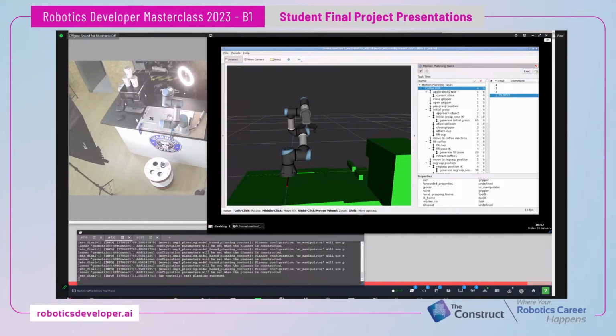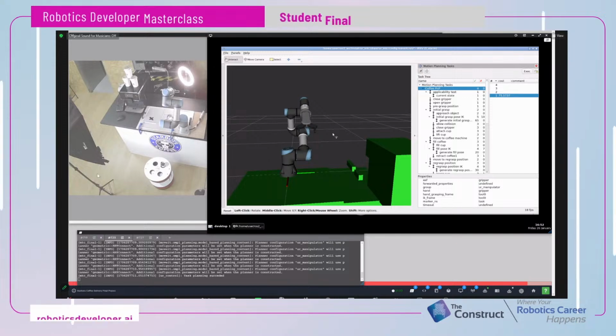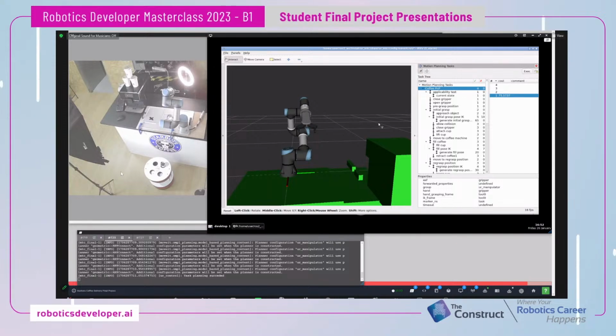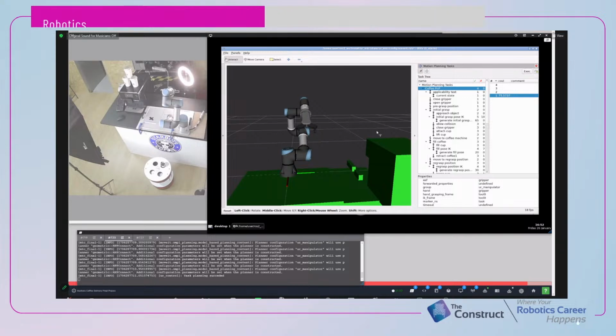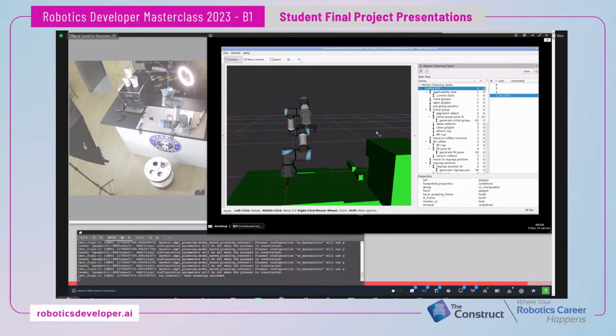This came down to the gripper by default. The RG2 gripper expects a 0 to, what was it, 160 value, I think. It's a value in millimeters for the opening, whereas ROS and everything else on the back end, the actual model, is constructed using what's presumably radian values of like 0.4, minus 0.4.